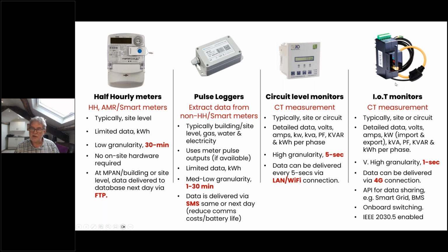These devices can also have onboard switching fitted, so we can start to switch on-site assets on or off, up or down. And the modern protocols for interaction with inverters, battery management systems, EV charging systems are embedded. So this becomes an on-site controller. And a selection of these can be deployed on-site depending on the client or the site requirements. These are in use today. It's not future, this is actually today.